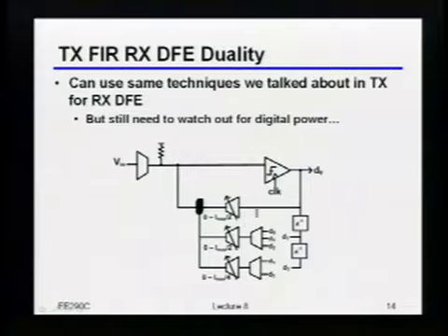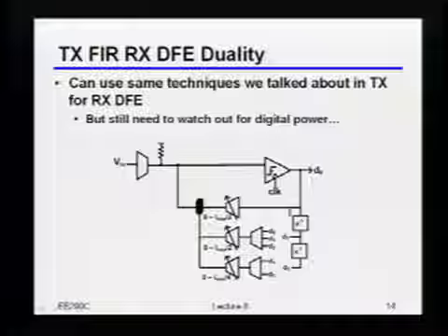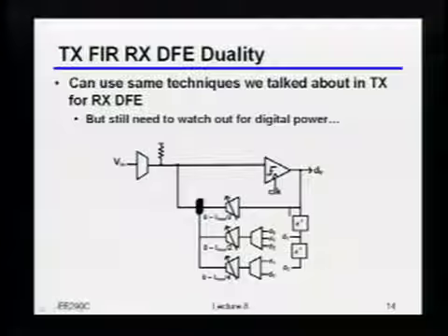Right, well, okay, actually, to be fair, I actually did because I put a D0 there, so I didn't play that particular trick, but you can imagine there's some games you could play where you do the muxing at earlier points in the feedback chain and then move flip-flops around. There's lots of games you can play there, but you're absolutely right.